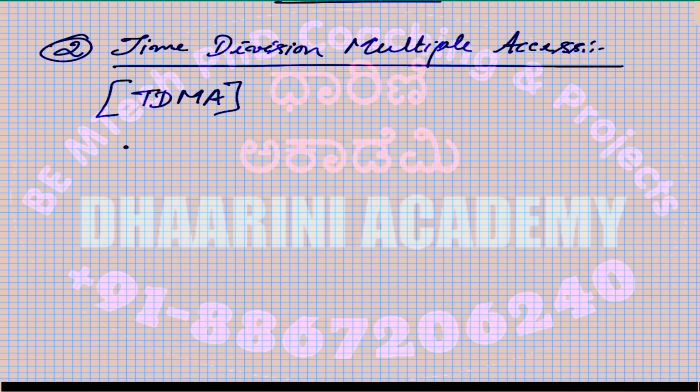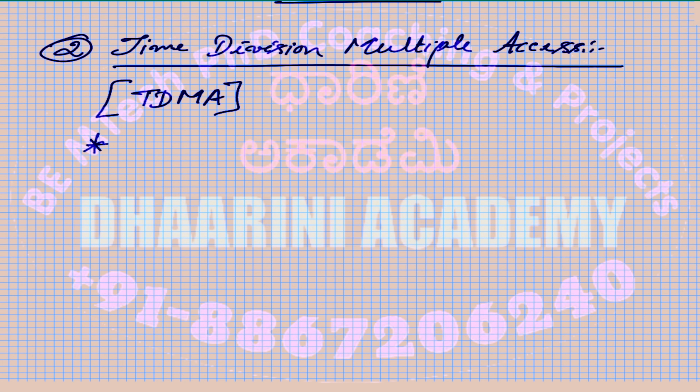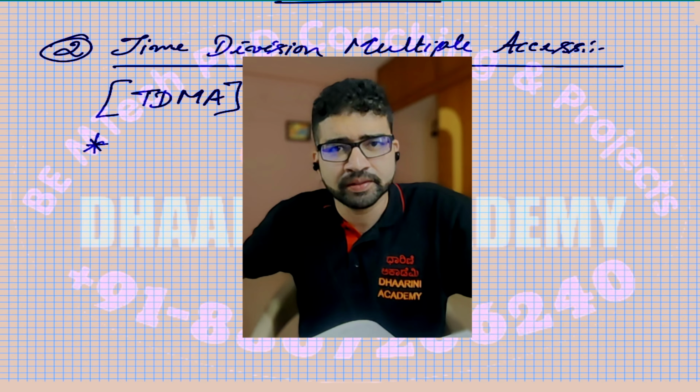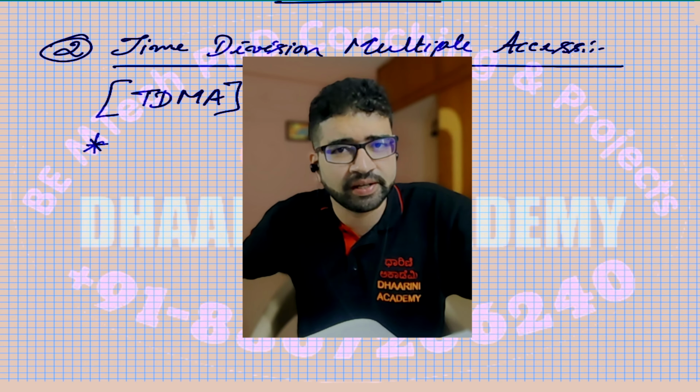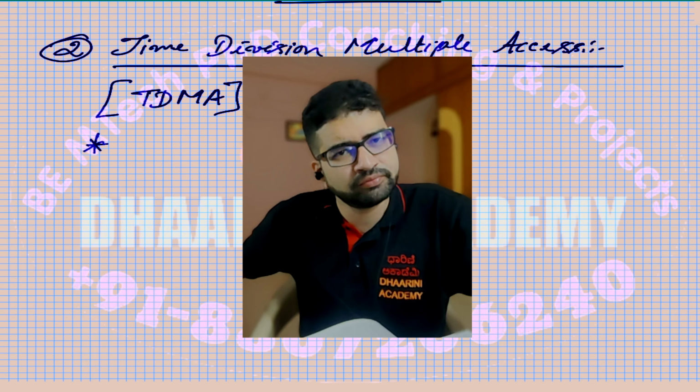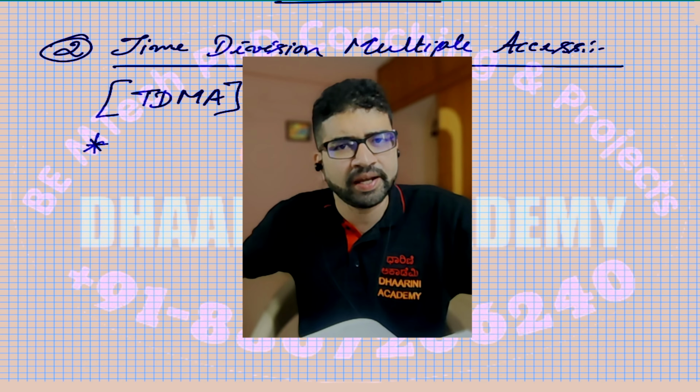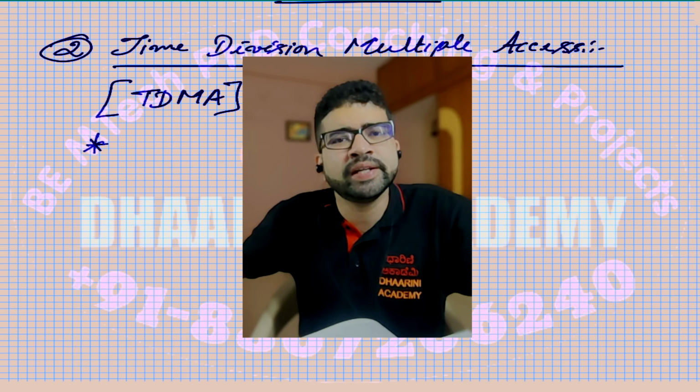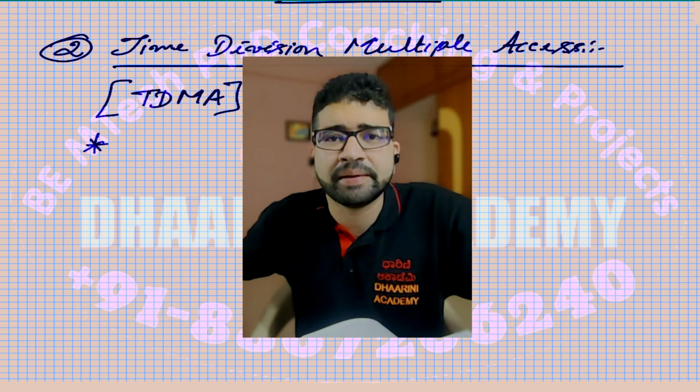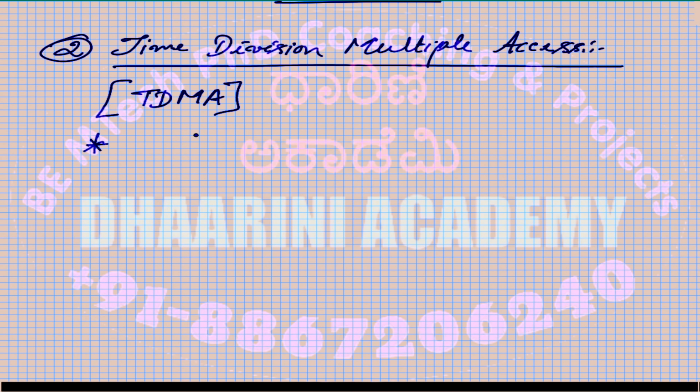All right. In this case, we cannot divide the frequency. In the sense, each user will not get a part of the frequency, but the user gets the complete frequency. The complete band is allocated to a user, right? But if you do so for the complete time, then other users cannot communicate. So what you do, you give the full band of frequency, but give it for a very short duration in time called a time slot. So this is the idea.